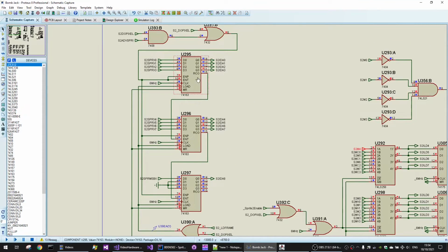So what this does is that every time it has completed the reading of all of the sprite registers, and it's passed the Y height test, it then goes into advancing the sprite X pixel coordinate in the Scanline RAM. And then every 6 MHz clock, it advances one more pixel until the sprite extent test turns this rendering logic off.